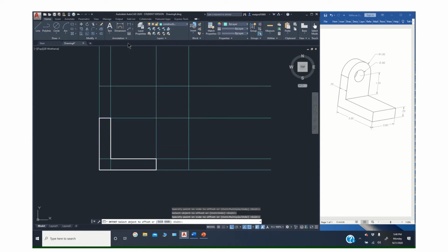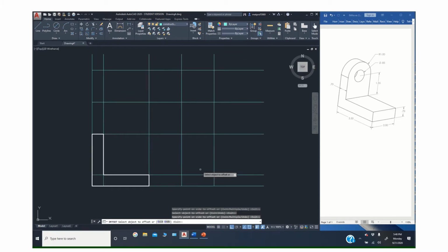I know this part is 2 inches wide. Seems to be a theme sometimes. Okay, so this is the space that my right side view will occupy. This is the space my top view will occupy. I will put a miter line on there, and let's go back to our 0 layer. So the right side view. Obviously, looking at the right side, I'm going to see that. Now I can't see this. This is just an edge when I'm looking directly at this side. And I will see this face right here, which is round. I'll get to that in a second.